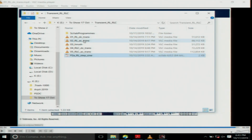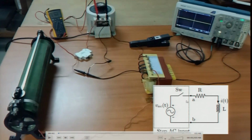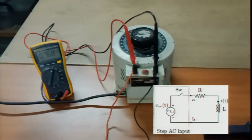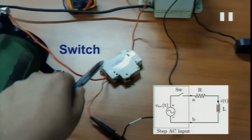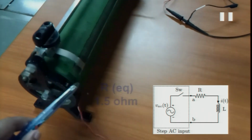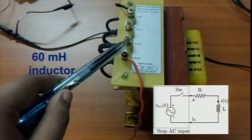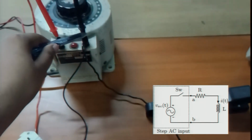We move on next to another experiment, which is the sinusoidal input. When you apply a sinusoidal input, the experiment will be shortly shown to you. Now you have got an AC voltage, and it is practically a similar kind of setup. We will increase the voltage using a variac, something which we will discuss a bit later. It is in fact an auto transformer. So, this is 1.5 ohm and you have got a 60 millihenry inductor. This inductor itself has some resistance which has not been accounted for, but that will affect our results as well.